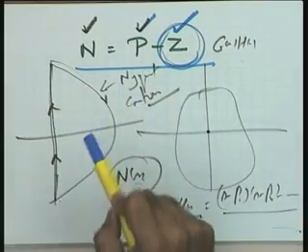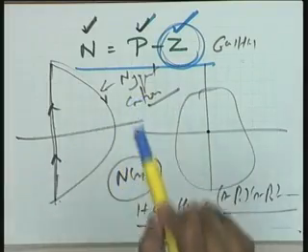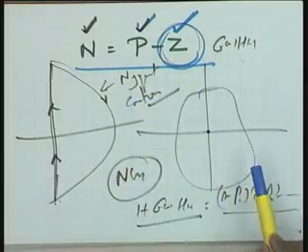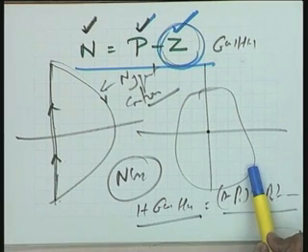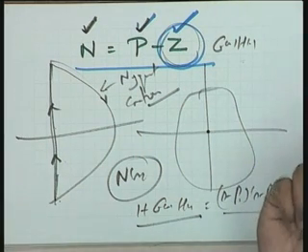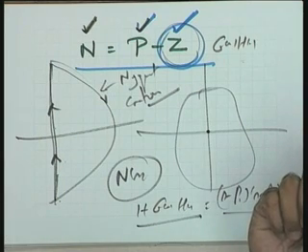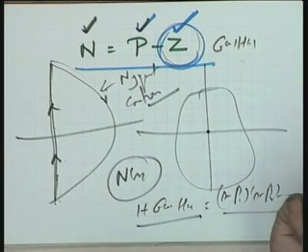If your original system is open loop stable, that is, the open loop system is open loop stable, there should be P encirclements. When I say open loop stable, it means P is equal to 0. This is what I wanted you to identify. There should be no encirclements of the origin.